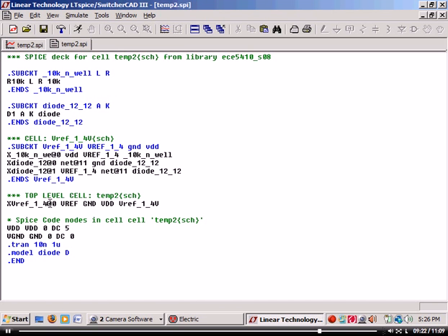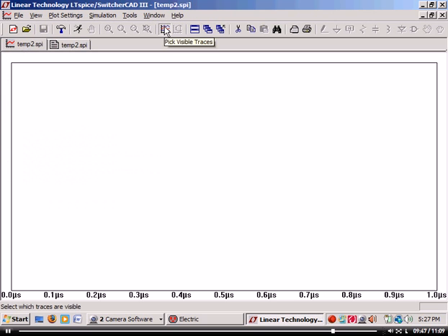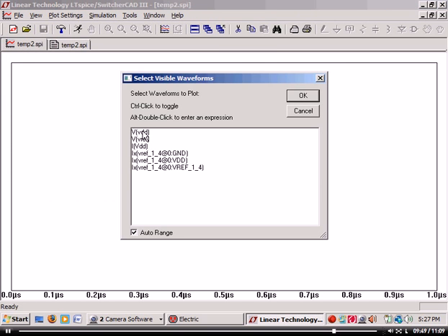This is my sub-circuit. I see I have 3 components there. And I have my main circuit, which is one line, which is just my X, which indicates a sub-circuit. And then the VREF, VDD, ground. They're nodes. It's like a subroutine. Okay? We ready to run? Are we ready to display? Let's make sure we got the right stuff first. So when we put VDD, we should see 5.